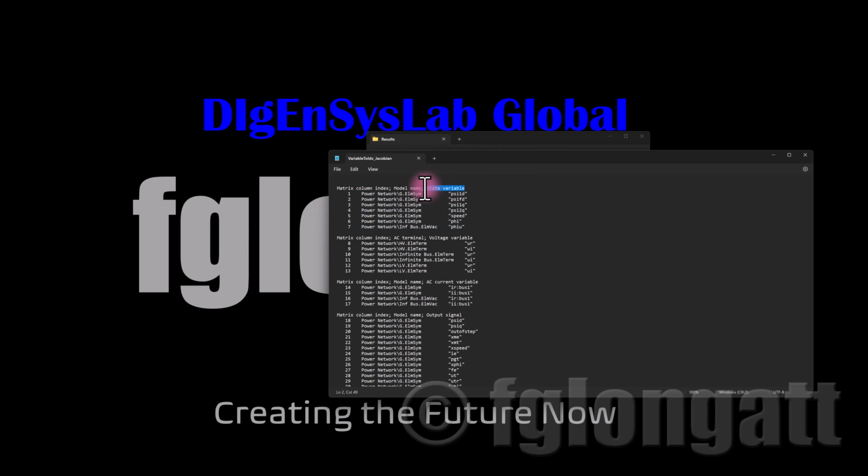You can see here we have 7 state variables, we have the voltage variable, we have the current variables, and the output signals. When we are here at the very top, we can identify there are 6 state variables, and those 6 state variables are related with the electromechanical model of the synchronous machine. As you can see, 4 of those states are related with magnetic flux.